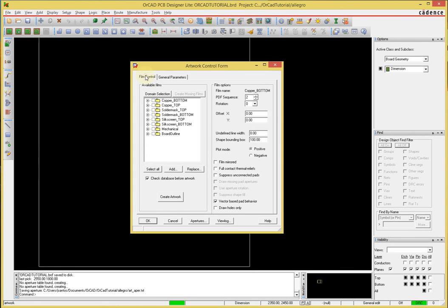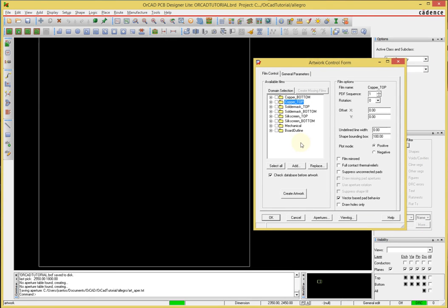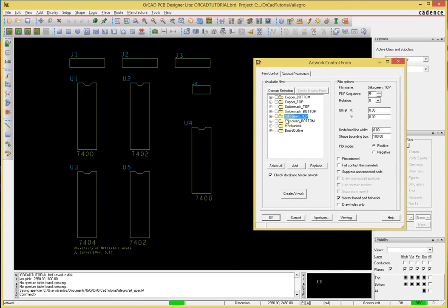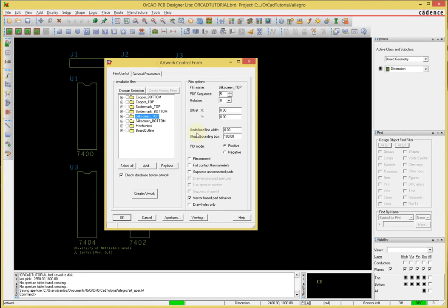Alright, let's go back to generating our Gerbers. There's one more thing we have to do before we generate some of these. Sometimes there are graphic elements that, even though they are visible, such as, to be precise, the silkscreen layers, if I display for visibility, it turns out that many of these graphic elements actually have zero width defined. So we can see them here, but when you generate the Gerber there will not be anything to see, because the lines have zero width.